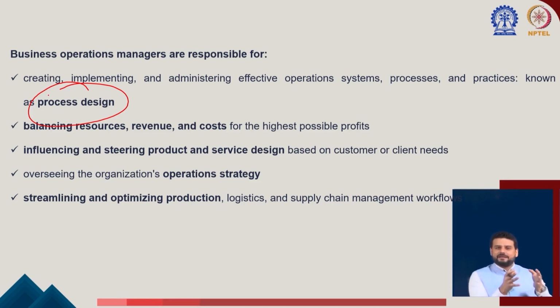Again, if I'm talking about the process design within quality, there should be some process for how they will ensure the incoming raw material quality. So you will come up with the quality standards, develop all the check sheets, record those data, and then finally say the lot is accepted or rejected. How will you ensure the quality during the process? Again, you will define different parameters at the critical stages, and that is also process design, right?